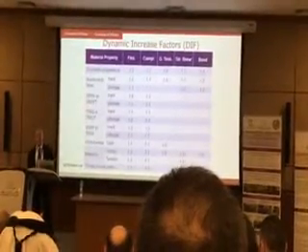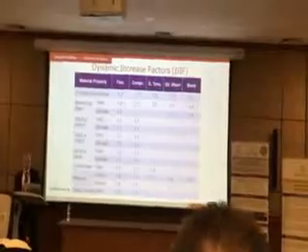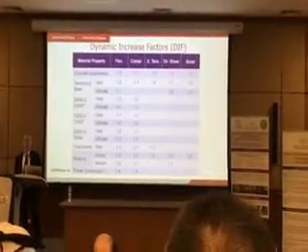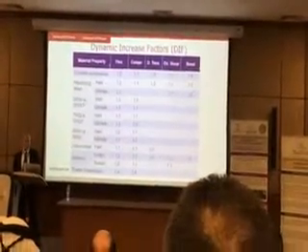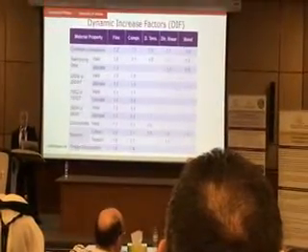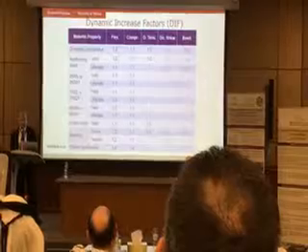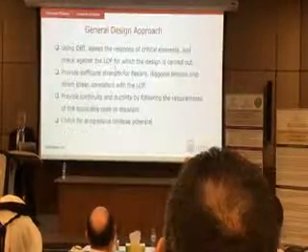So these are the tables now I will show you for flexural, concrete compression, axial compression, diagonal tension due to shear. As you can see, we are permitted to increase concrete strength 10% to 20% to account for dynamic increase factor or strain rate effect, and steel yield strength again to 20%.